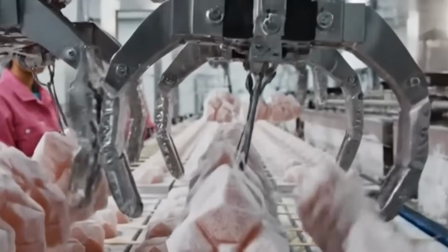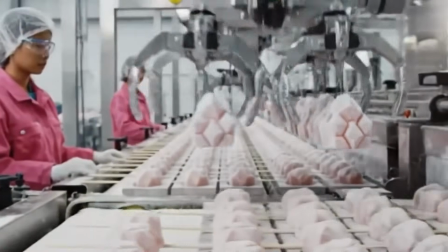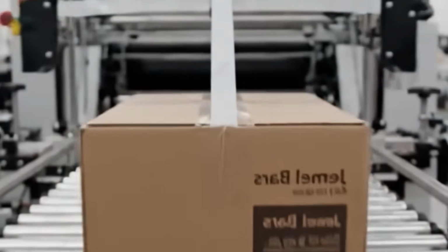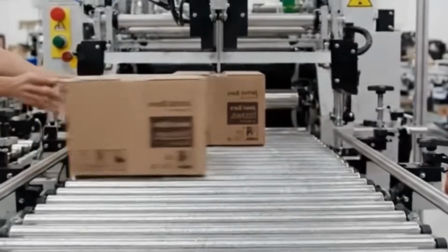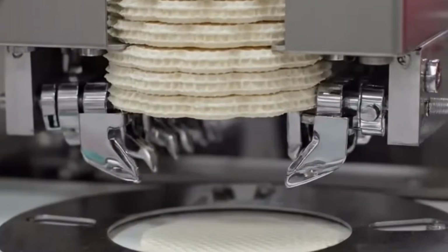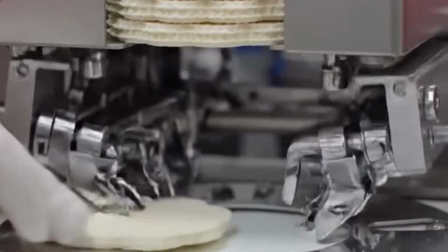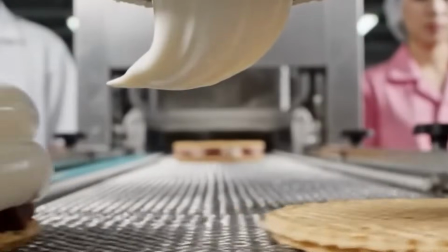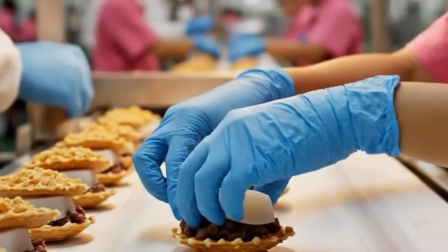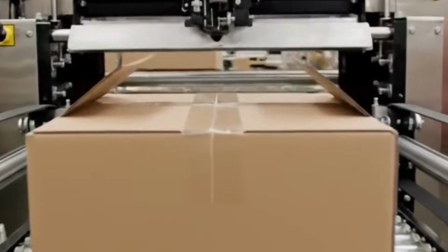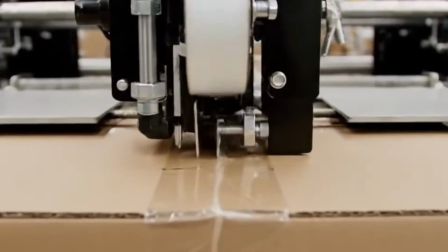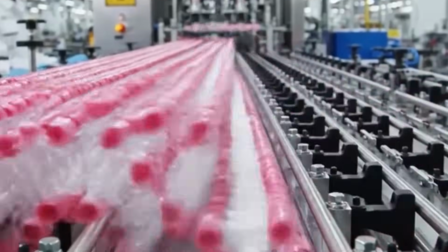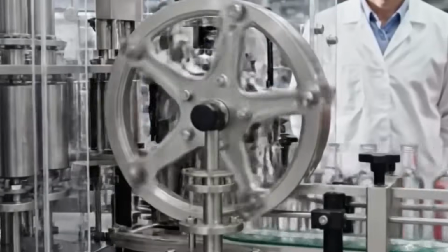In molded systems, the ice cream is deposited into polycarbonate molds that travel on a carousel immersed in a brine solution held at 25 to 30 degrees. Product solidifies inside the mold within 8 to 12 minutes, depending on volume. Once hardened, sticks are inserted mechanically into the semi-solid mass using servo-driven arms. Demolding is achieved by briefly dipping molds into warm water baths and using pneumatic pistons to eject the bars.